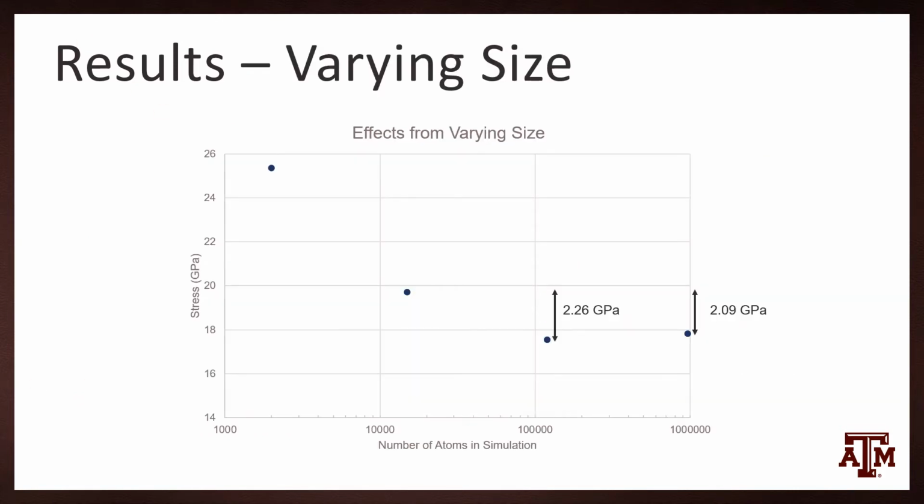I investigated several possible effects influencing this vertical shift in cavitation strength. First, as mentioned previously, my simulations are run with 3 orders of magnitude fewer atoms. To find the effects of this, I varied the size of a single boundary up and down orders of magnitude. The rest of my simulations were run at the second point, with about 25,000 atoms, and I would need one more data point larger to reach the scale of the simulations from Chen et al.